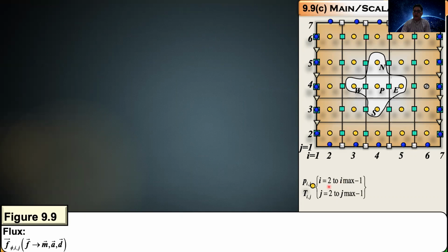So the loop that I presented earlier, in the earlier topic on computational heat conduction and convection, where the yellow circles were pixels for temperature and the green squares were for Qx, is used here to calculate the enthalpy flux, the conduction flux, and also the mass fluxes. We are following a convention where the running indices for the positive faces correspond to that of the control volume on which it lies. So for the fluxes, the running indices correspond to those on the positive faces.